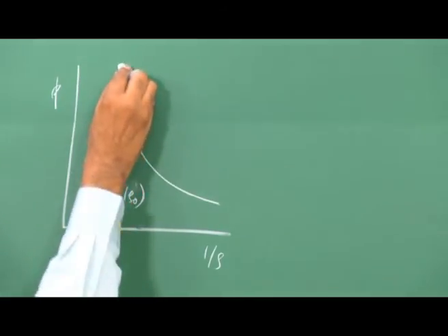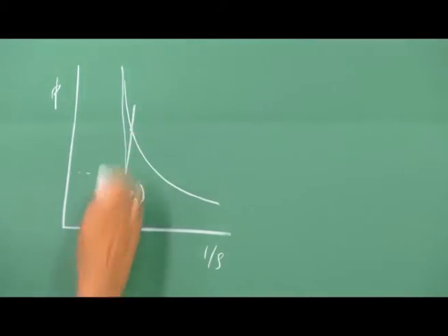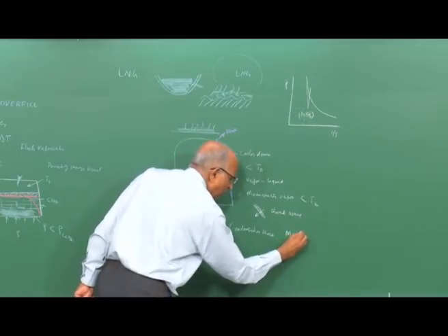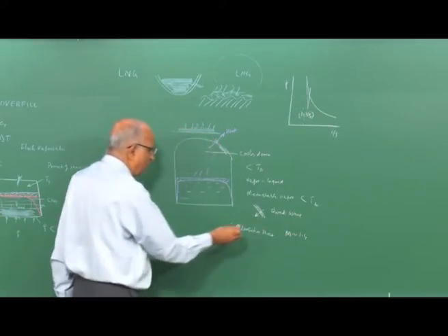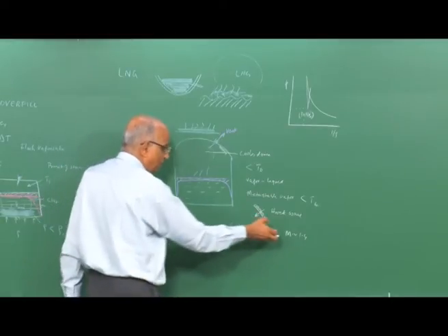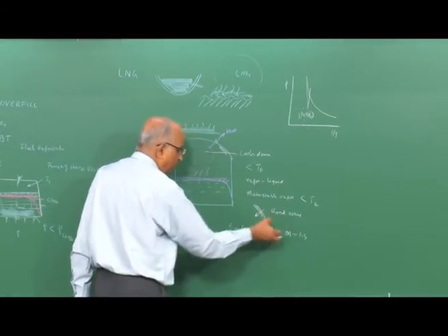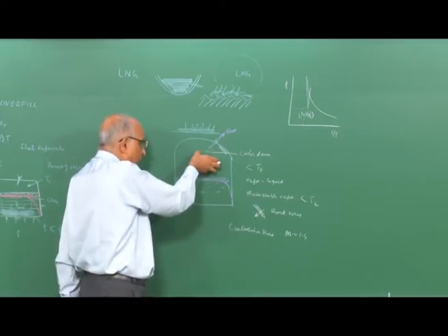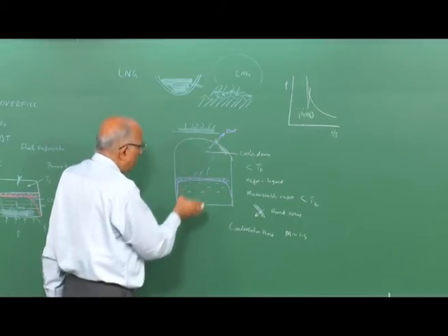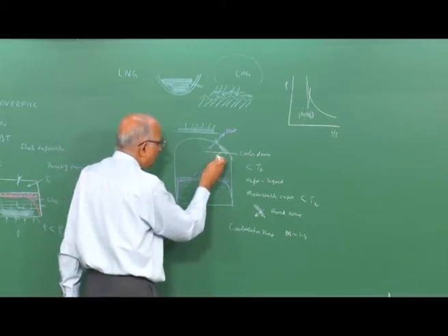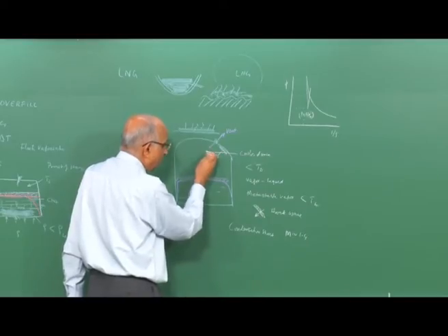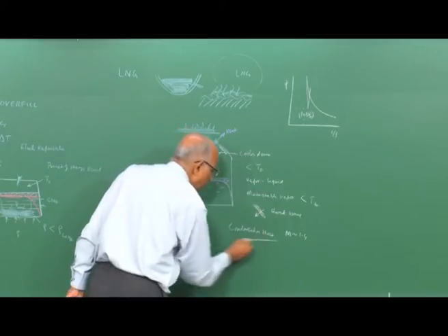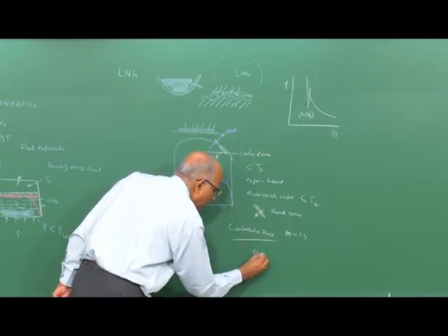I can always form a shock with some particular velocity, and the Mach number of the condensation shock is in general small. It is of the order of 1.4. In fact, these are encountered in any process in which you have a rapid cooling of the vapor, like in a wind tunnel, or in the case of storage vessels. But anyway, you have a shock, and this shock will increase the temperature, will also increase the turbulence, will lead to more flash vaporization, and this could also be a cause for explosions of storage vessels.